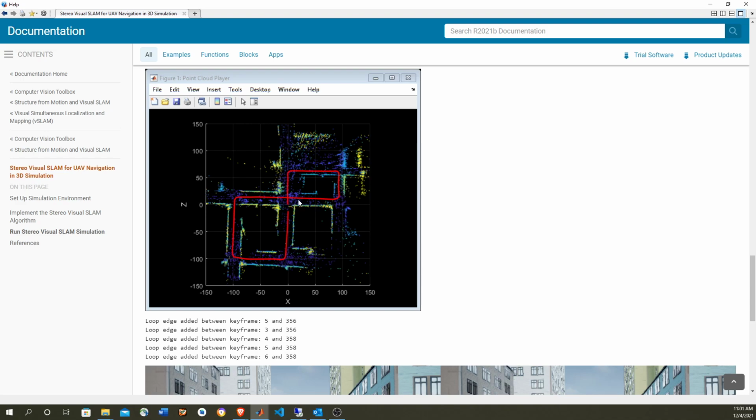database with the backup features for the ORB features that we are using for each frame to detect if you happen to be in the same place that you already visited. And for example, in this trajectory you always visit new places, but once you get here the set of features matches the one in the database, so a loop was detected, and that's the end of the simulation.